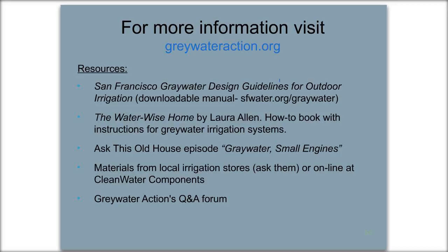If it's your sewer line, if you have a properly plumbed residential home, all of your water should get to the main line of your sewer by itself. If you have problems with your sewer line, like trees have intruded into the line and disturbed it, and you don't have good flow going out, then if you add a graywater system, you potentially could see some problems that you didn't notice before, because before your shower water or your washing machine water was helping to push solids through. So graywater might highlight a problem that was already there. It shouldn't cause a problem, but it could expose a problem.